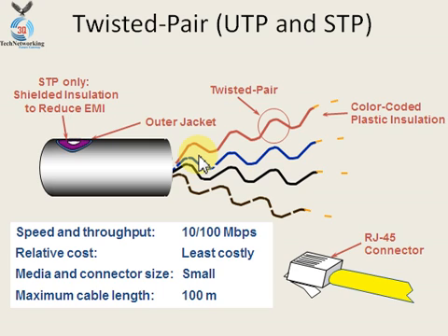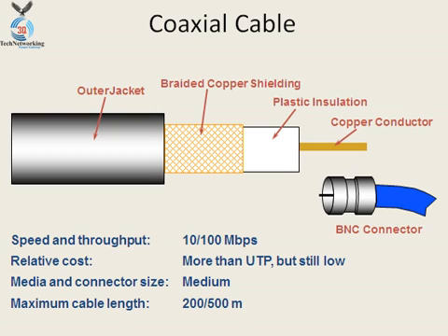And coming to coaxial cable, it is a kind of copper cable used in cable TV, between a community antenna and user homes and businesses. First let us see why it is called a coaxial cable. It is called coaxial because it includes one physical channel that carries the signal, surrounded, after a layer of insulation, by another concentric physical channel, both running along the same axis. The outer channel serves as a ground.